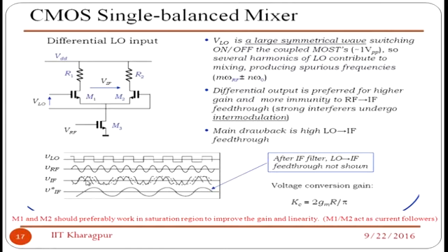Switching means if one of them turns on, the current is passing through the transistor M1, but whenever it tries to fall down, the other one starts and the current pushes back. So there is a transition time. If it is like that, you cannot have a pure sinusoidal wave. You can have a distorted kind of sinusoidal wave. So that's why you got this kind of distorted sinusoidal signal.